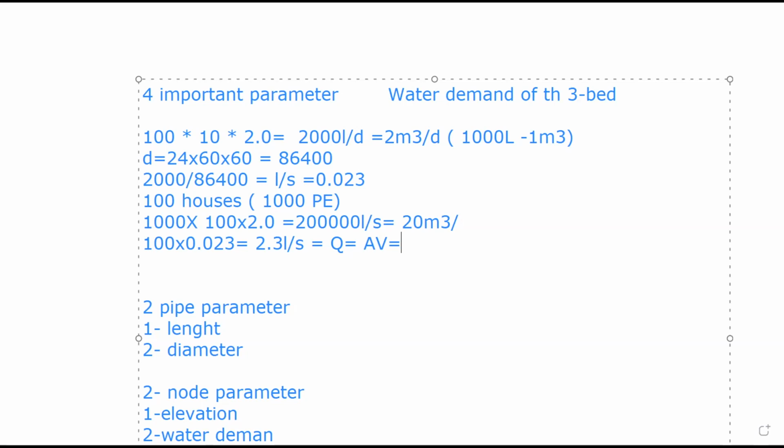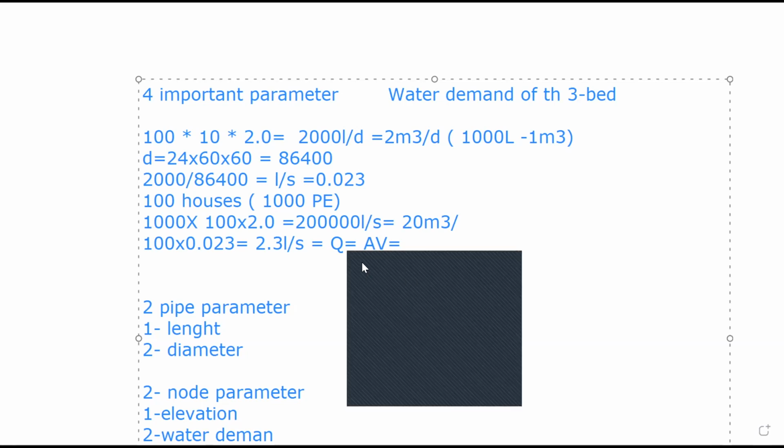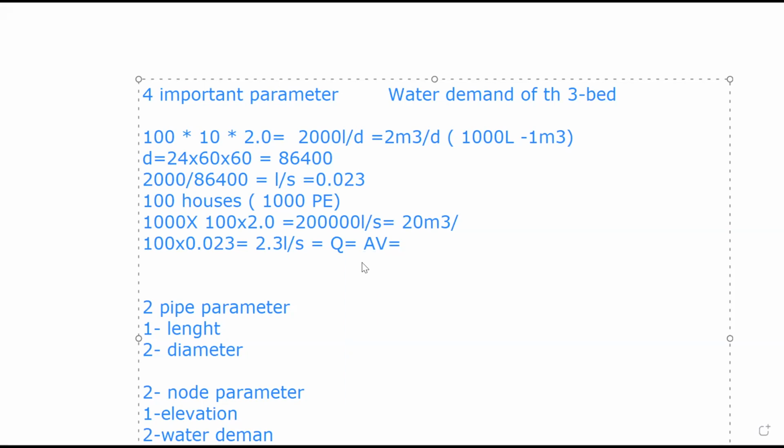If you now go to that chart, it's called a nomogram. There is the one for 0.1, the one for 0.4, and the one for 1.0. All of them depend on the type of material. So here, we're using PVC pipe, which has the lowest frictional factor.